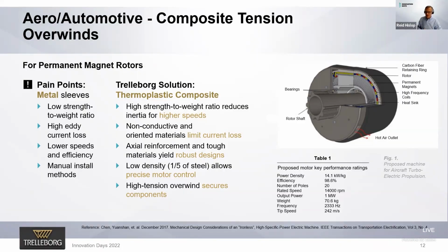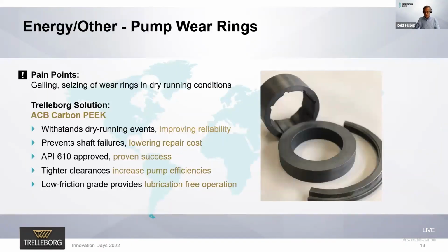The automated fiber placement process can induce a pre-stress in the material as well, prior to placing onto the magnets, up to 1,000 pounds of tension, to increase high radial compression on the magnet assembly. These can be chilled as well during manufacturing to induce further radial compression. So what we end up with is an electric motor that is able to operate at its highest demand. So there's some increased interest here regarding these electric motors by themselves. Very, very important application for us at the moment. Happy to chat further with you as we move along.